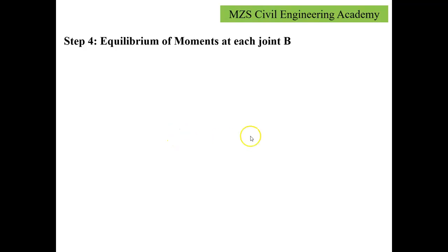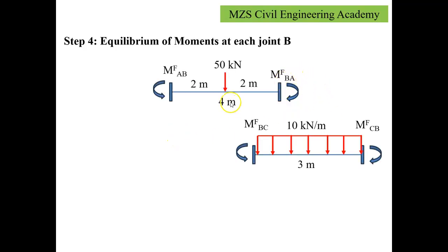This is the slope deflection relation which we have reached at each joint. Next step is to write the equilibrium equation at the joint B. For this we'll have the equilibrium of the span moments. If I talk about the joint B, I am getting span moments which are encircled in dotted lines here. So I will take a balance of these two. Means MBA plus MBC should be equal to 0. This will be the equilibrium condition at this particular joint.